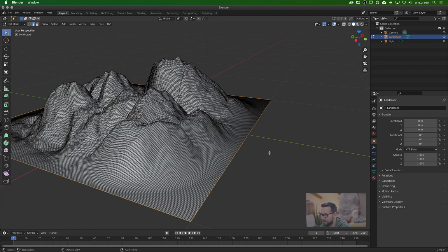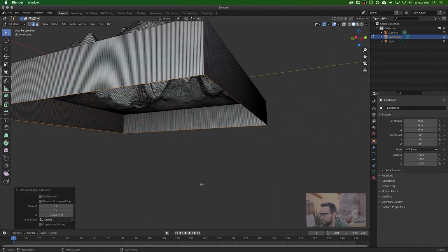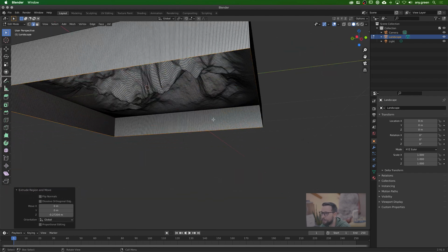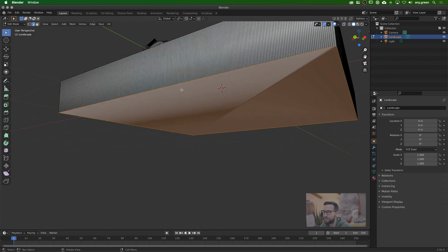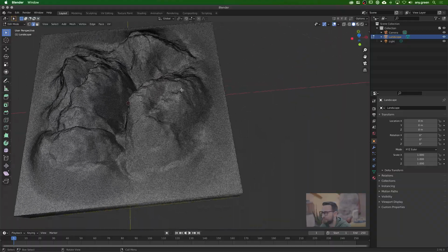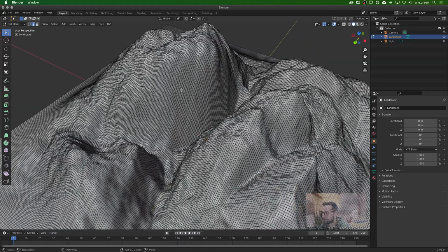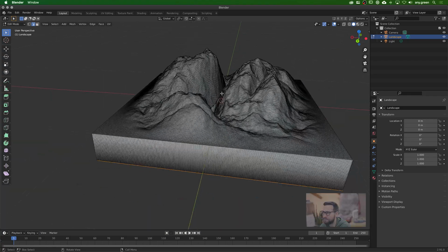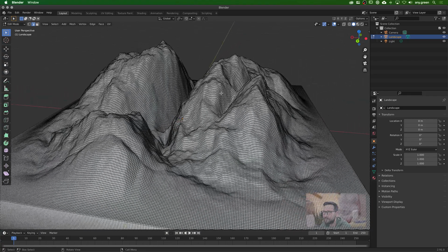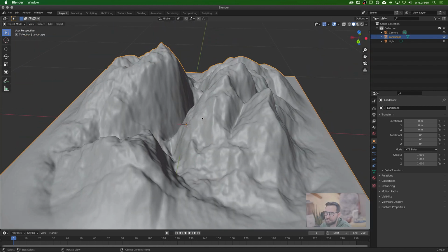Let's switch to the edges, and what if I extrude it now? It's moving down, perfect. So I hit Z to lock it and move it down so I really get a nice big volume here. And then I fill the bottom by hitting F. And then this is closed. The bottom part here is not clean geometry, but that's fine. Later on, once we remesh this, it will be all right in the end. I'm already thinking if it does make sense to do it on the entire mesh. I mean, it's already pretty dense, so my computer might die, but, well, let's see.